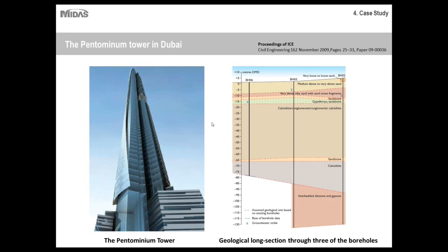Numerical analysis was used to evaluate the overall pile raft response under various static and wind loading combinations. Because of all the different loading combinations, numerical modeling was especially useful to take all of those into account. There were also some techniques used to optimize the foundation design, including preliminary design testing. To optimize the design, a parametric study was performed in which several different variations of pile configurations were tested, not only for safety, but also for economy.